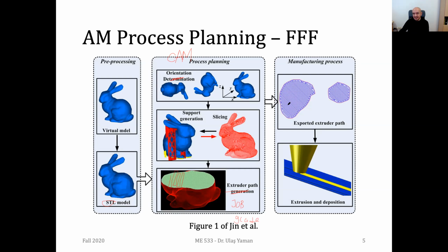If you look at the slice here, we have some shells. These shells are again related to your mini project. Let me draw this. Assume that is the outer boundary, and then we have a shell here. We prefer to have at least 2 shells so that the part will have some amount of strength.